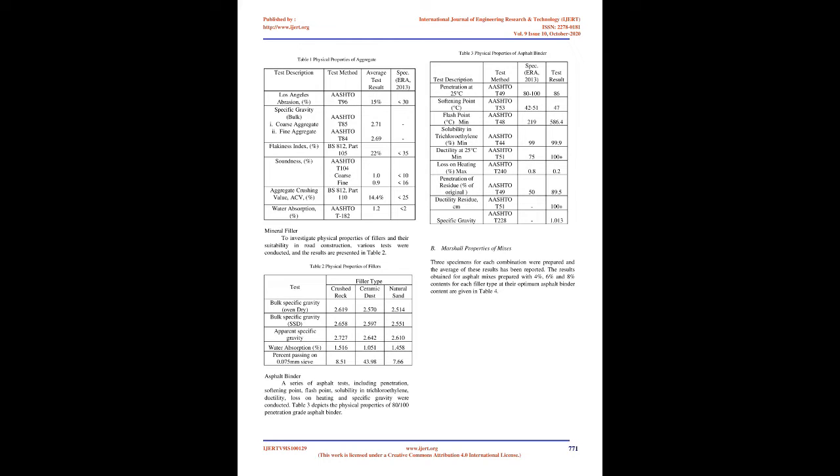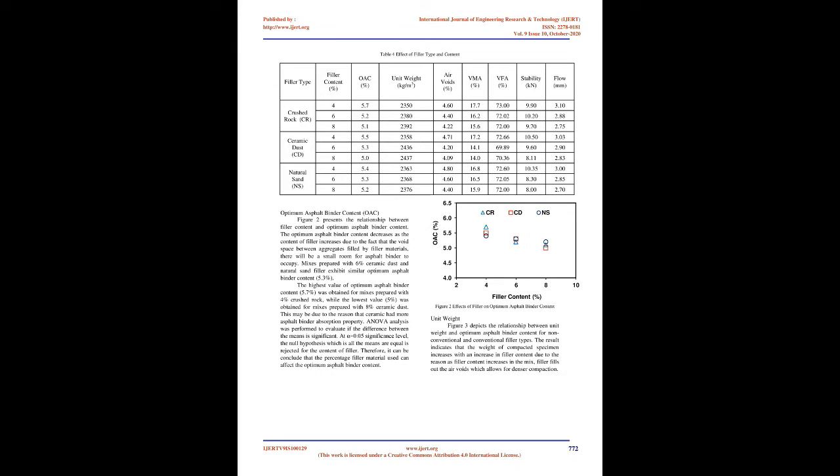Tensile strength ratio, TSR, is the relation of the strength values before and after water storage. The indirect tensile strength, ITS, was calculated using the equation given in ASTM D6931: ST equals 2000 P/(πDH), (1), where ST equals tensile strength, kPa; P equals maximum load, N; D equals diameter of the specimen, mm; H equals thickness of specimen, mm.